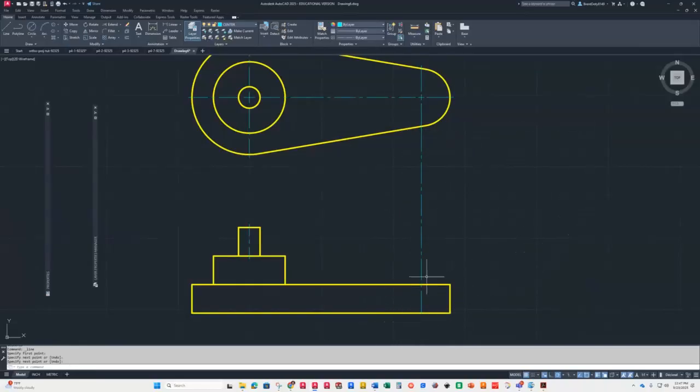Now you're probably saying, well, why didn't you just draw that in? Well, then I'd have to make sure it's an 1/8 inch past the edge of this line, an 1/8 inch past the edge of this line, when all I have to do is go to this guy right here, copy, and then pick this intersection right here at the top, and this intersection right here, and I've got my center line in the right spot. That works pretty well.